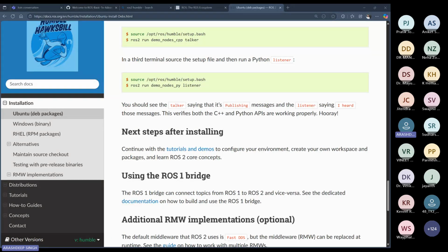Each node in ROS should be responsible for a single modular purpose, like controlling the wheel motors, publishing data, and doing only one particular task, so that it does not become a complex system. So what ROS is doing is just breaking down the complex system into nodes, and if we need to debug something, we can figure out which node is malfunctioning, where the problem is. So we need not worry about the other components. Each component has a node.